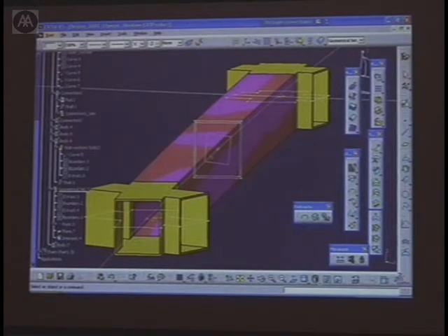You could say, who cares? It's 60 meters up in the air, nobody's going to see it. But the problem is you're going to get very bad weld joints, you're going to expose yourself to steel corrosion. And so those are decisions that have to be made by the design team that affect, on one hand, the outcome of the project, but also the manufacturing process.